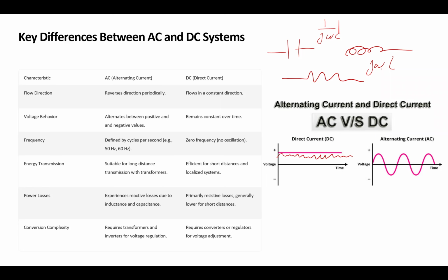That total power we call apparent power, and we show it by S. It includes the active power that works for us, and the reactive power that we need to deal with L and C and that phase displacement in our system.